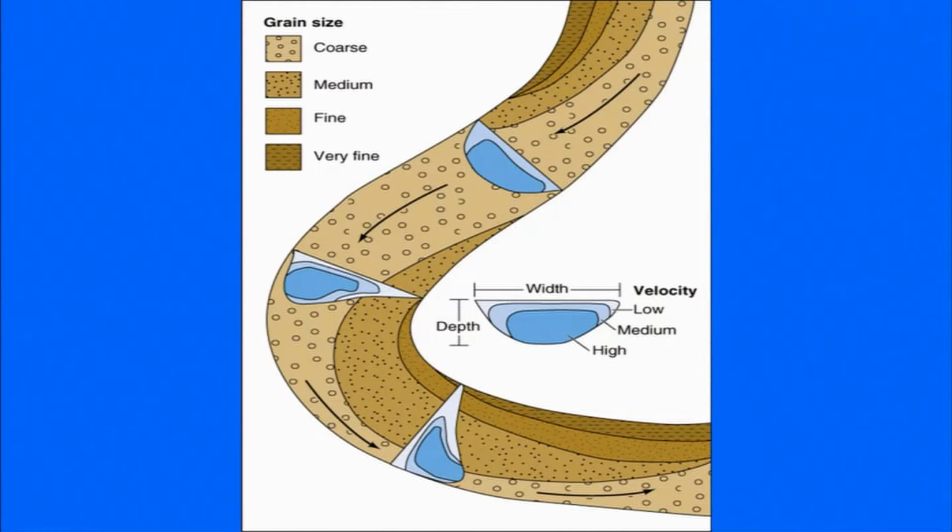Throughout the channel you will see that the grain size of the material varies from place to place. The point bars you will mostly find in the finer domain, so the point bars will comprise finer to medium sediments, and the portion having higher velocities will have coarser deposits. Bed load will mainly be seen on the outer side, the portion which is eroding, and on the deposition side you will mostly see finer deposits.